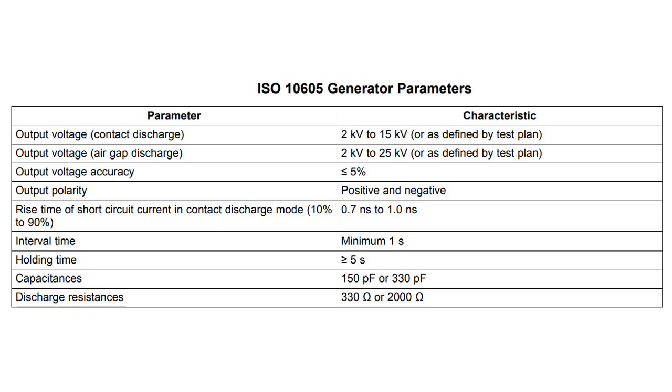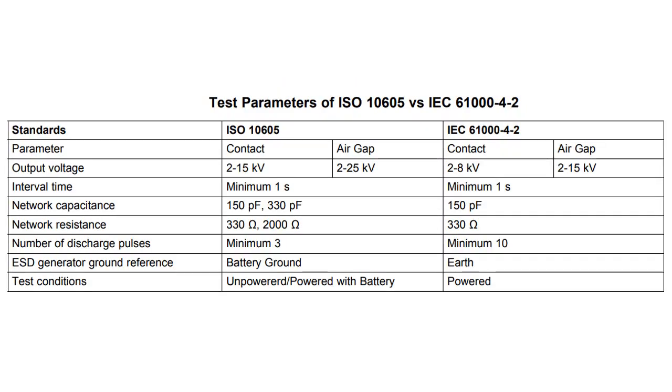2. The test is performed at different resistance values to simulate the discharge of a body directly and through a metal object. It is also performed at different capacitances to simulate a discharge both inside and outside the vehicle. While there are a variety of other differences, ISO 10605 is quite similar to IEC 61000-4-2, and it is the industry standard for ESD protection devices in automotive applications.